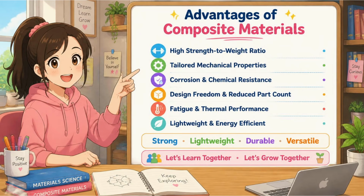Engineers can control the properties by changing the fiber orientation, volume fraction, thickness, and laminate arrangement. So instead of accepting whatever properties the material naturally has, we can design the material according to the application. Many composites also offer excellent resistance to corrosion, moisture, chemicals, and weathering. This can reduce maintenance and increase the service life.